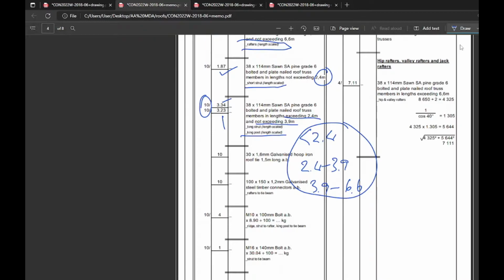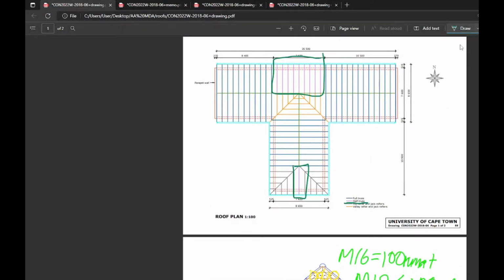Go down. Hoop iron. This one is interesting and quite logical, which is why I enjoy it. We will take a look. You are putting hoop iron on a half truss. So a half truss only has bearing on the wall plate once, because it's half. Okay, it's pretty obvious. But if you're going fast in an assessment environment, you could overlook it and just put 2 per half truss. It's 1. Why? The other side is actually bearing down on what we're going to put in later, which is a ridge beam.